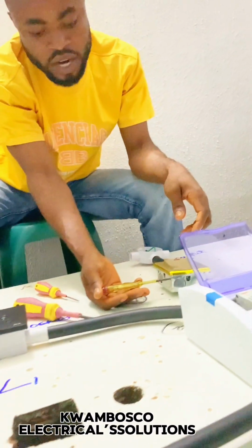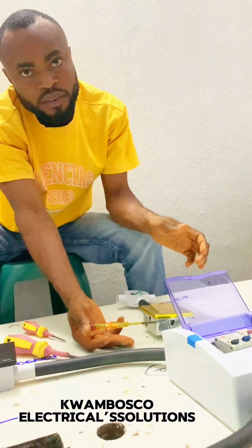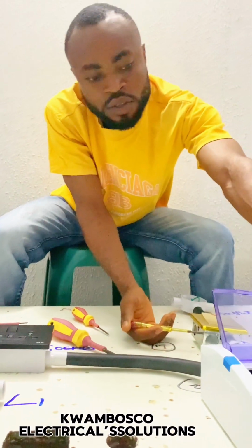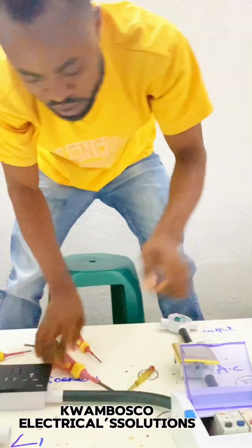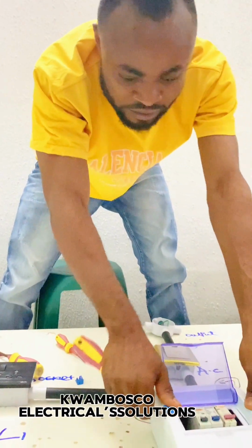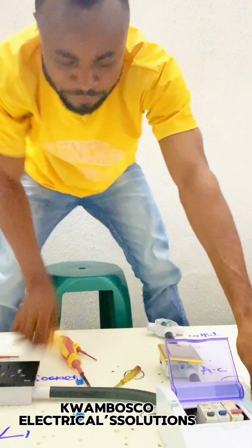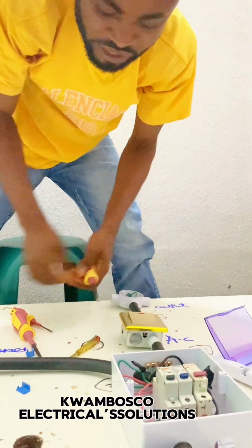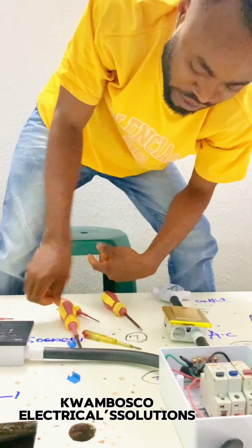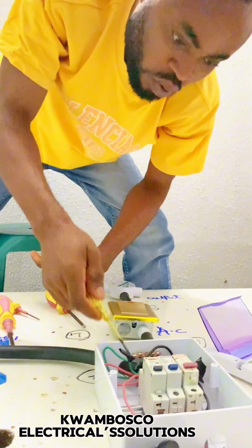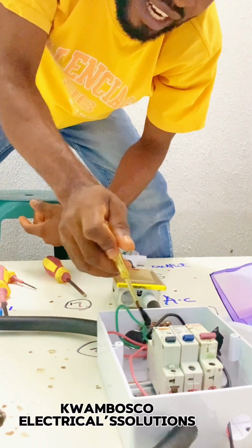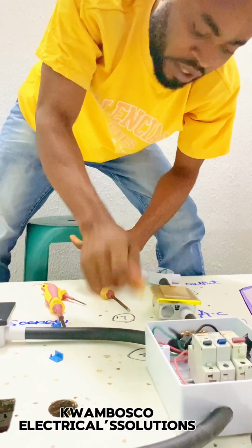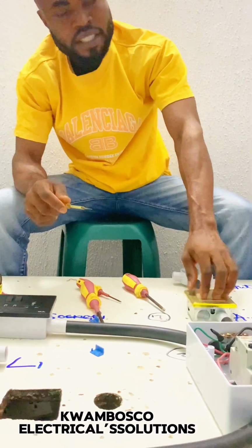If you come here again, no light. But if I on this one, the light is on, the fault is still here. So what you do is, you off this one, you open your distribution board to know if the problem is from here. And you look carefully, the earth cable is not in contact with any live wire here. So now the distribution board is okay, the fault is not from here. So our fault is 100% from this one.